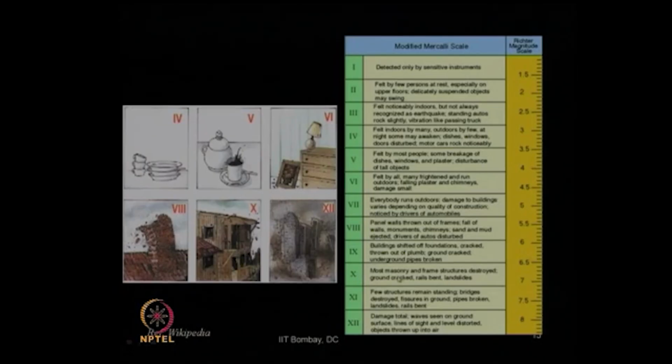So, this correlation relates the other way around, that is where we will say an earthquake intensity scale of say 9 has been measured or observed by an observer qualitatively, that may correspond to a typical magnitude scale of 6 to 6.5. So, we can go from this to this scale, but not from this to this scale. Okay? So, this is the correlation which we can obtain from this chart.